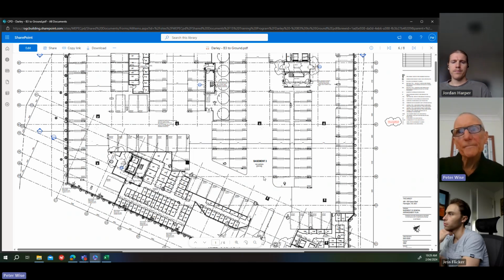If you're on B1, all the cars from below B1 are going to pass through B1 before they go out of the building. So they're going to contribute to the CO level in B1. So you've got to consider all of that. But at B3, all the cars are going up from B3, so there's nothing below it. Does that make sense? Yeah, that makes sense.